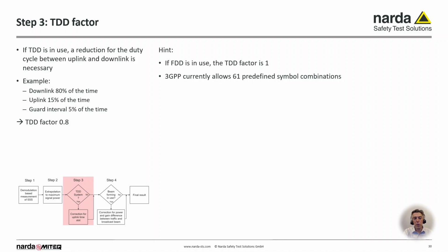There, the mobile operators talk to each other, and they said, look, we all transmit at the same time and we all receive at the same time. For signal quality, we don't want to have the situation that, for example, T-Mobile is transmitting, the base station is transmitting, and Vodafone is receiving at that time. This could cause interference if there is any kind of PIM or something like that on the air. This can cause problems. So they say we don't use this flexibility, but in terms of better service, we all synchronize our services and we all use the same uplink and downlink timing.